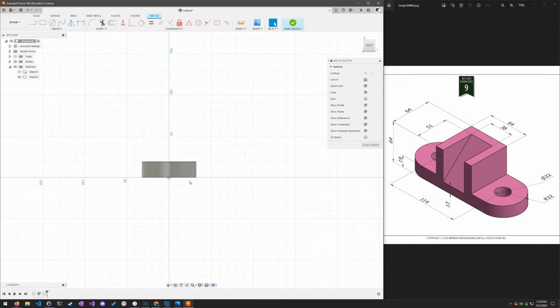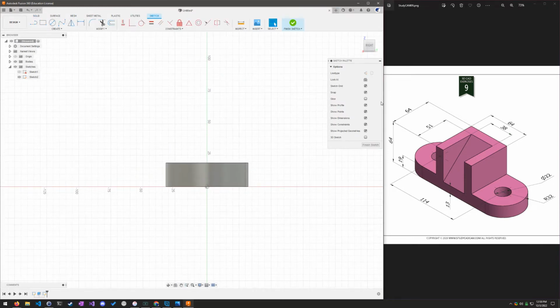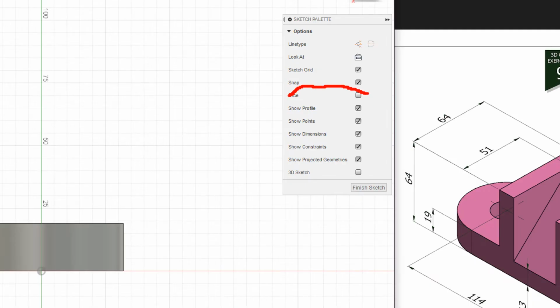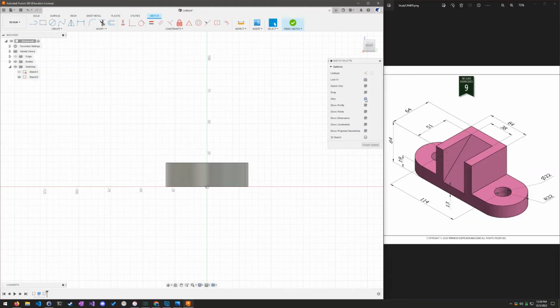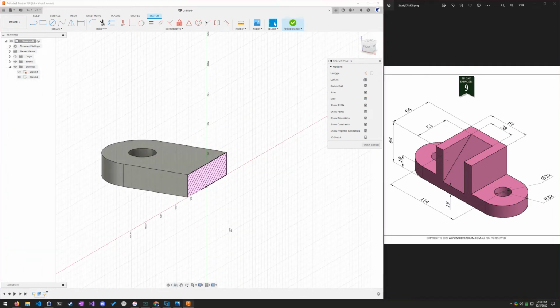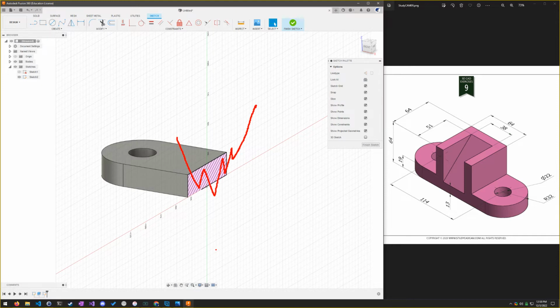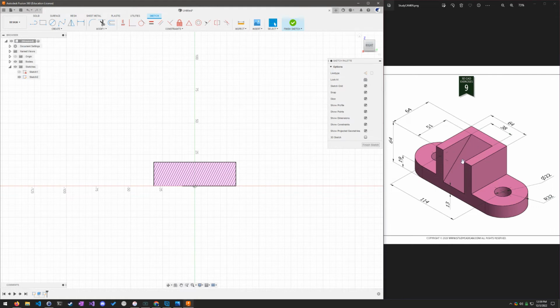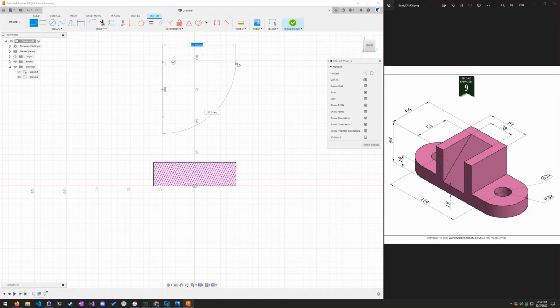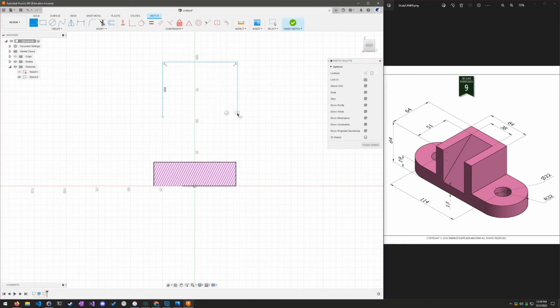And now you'll notice when I click on the square, if I select this option right here, slice, I can actually see where I'm drawing with this cut in half like that, which is really useful because I'm basically going to draw this box and extrude it outwards in both directions. But let's go ahead and dimension that box. So I can use the line tool and make a line that goes up, to the right, and down. Then I can do another line that will connect like this.